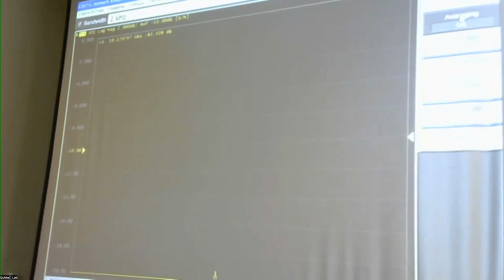Okay. Now coming to the IF, why is it called IF bandwidth? In all microwave analysis which involve changes of frequency, usually we will have three terminologies which are used: local oscillator, RF frequency or radio frequency, and IF frequency, which means intermediate frequency. It's just a fancy name for saying low bandwidth. Usually it's because you will take two high frequency signals, which are slightly different, and create a difference frequency, which is a smaller number, and that is this intermediate frequency.